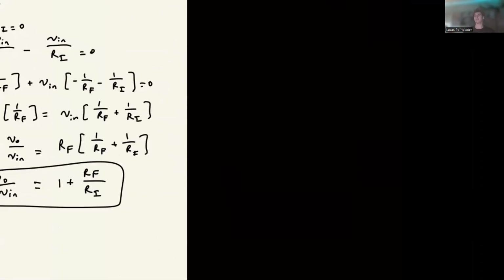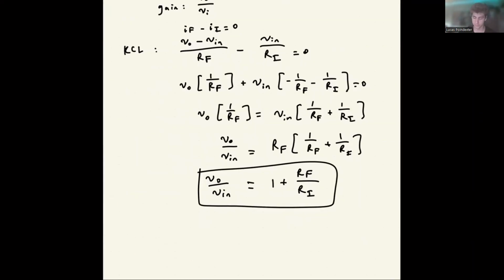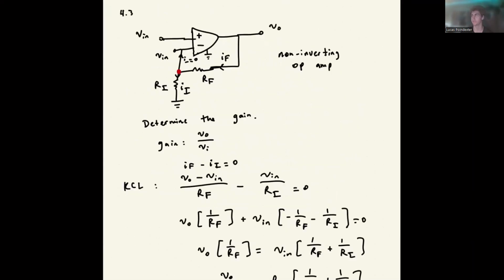Also, not in relation to the ground, but in relation to the voltage supply. If you're actually using an op amp in a circuit, would that just be hooked up to a power supply or something like that? Right, so it can actually get kind of difficult making these kinds of circuits, because you need some kind of negative supply, and that's not necessarily a trivial thing to do.